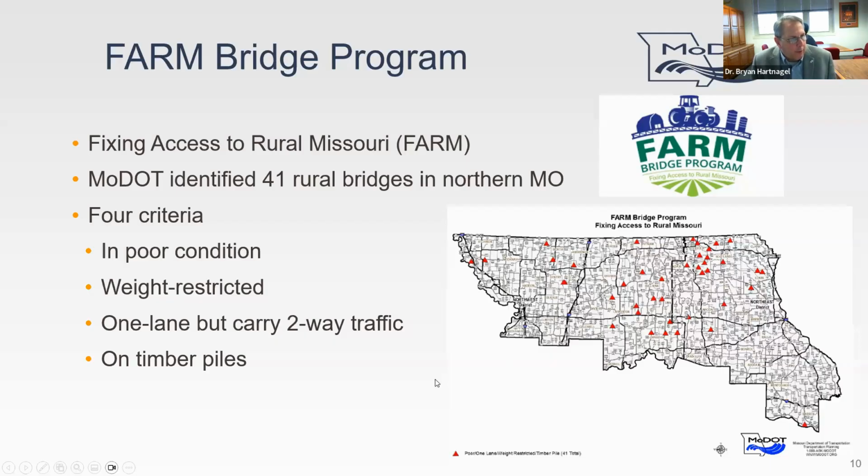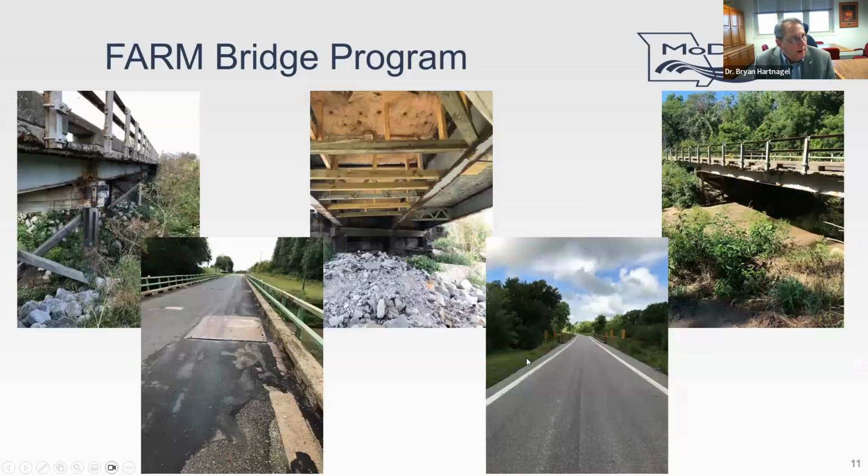So many of these bridges were built when the substructure was 6 40-foot creosoted timbers, right? For the intermediate bents and the end bents. So those were the criteria we used, 41 bridges. And here's a picture of some of these. Top left there, you can see timber substructure, substandard barrier rail, just general deterioration of the deck where the curb outlets are. We were talking earlier about Minnesota and Wyoming, where Dr. Michael Barker's at Wyoming and Natalie's obviously in Minnesota, and temperature.